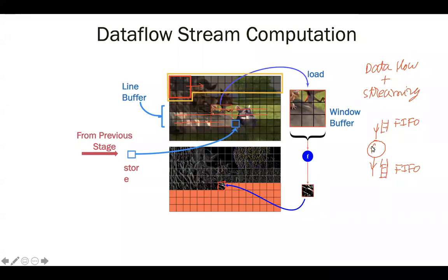And why is this a streaming model of computation? Because we are streaming in the image from DDR memory onto the FPGA fabric, and we are doing computations there. So these two keywords I would like you to remember, because they are very important design principles in coming up with architectures to solve new problems.